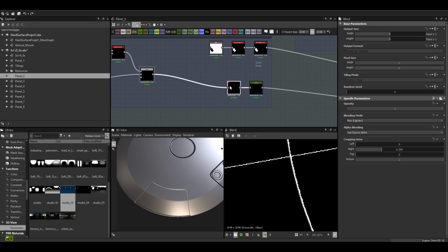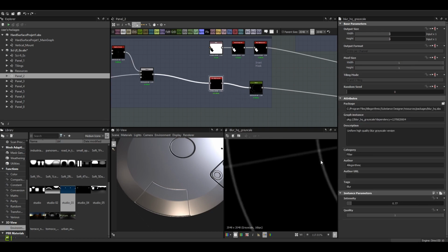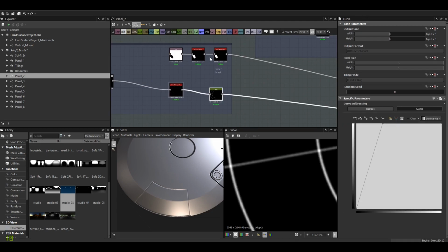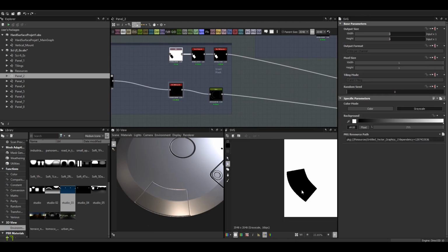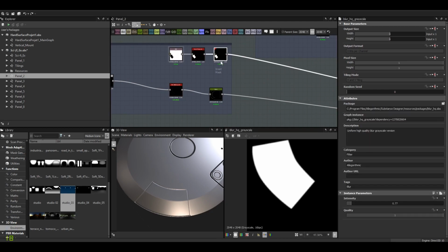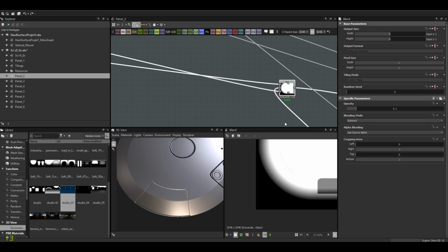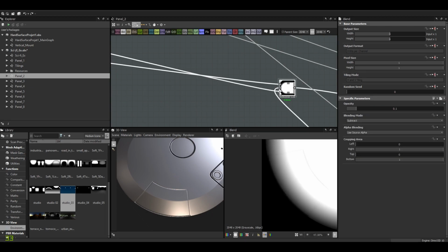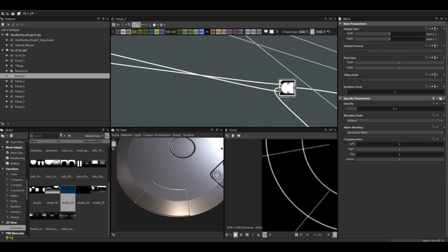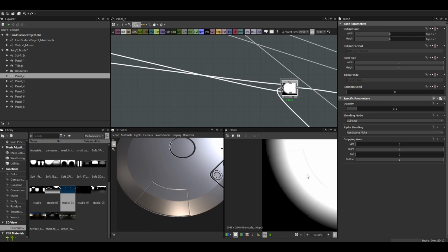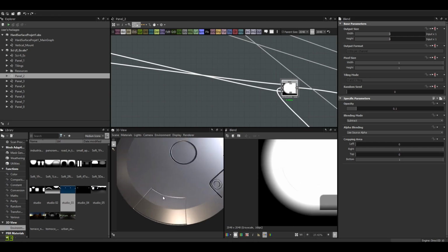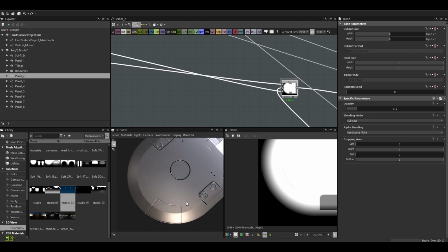We're not there yet, so I needed something else. I guess one could say I cheated a bit for this one as I used the SVG node. In other words, I drew a mask by hand to keep only what's needed to be kept, this area here. Then I just subtracted the lines from the main shape. And the mask helped me make sure the subtraction was restricted to the required zone. And we have it. It was a bit tricky, but as always, the discussion is open. If you have a better idea for doing this, you can share it.